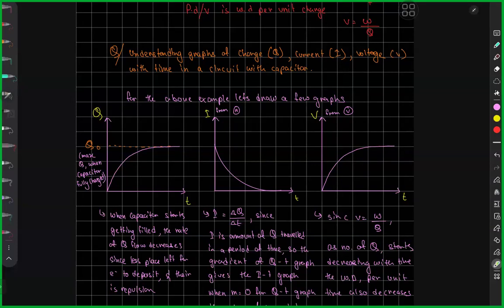That is the key idea over here. So analogous to that, I have my graph over here. Initially, it's max current because a lot of electrons are flowing, and eventually, as you proceed and plot, the current drops down to zero. Again, the circuit is still complete. It is not that I've opened the circuit or anything. It is simply that the charge buildup is complete for the capacitor.